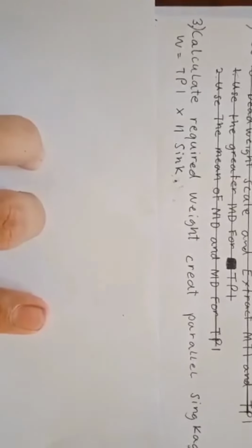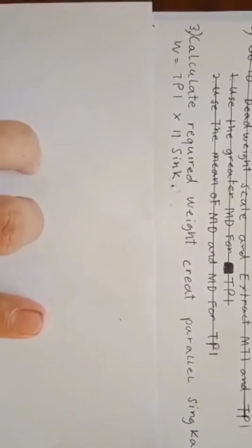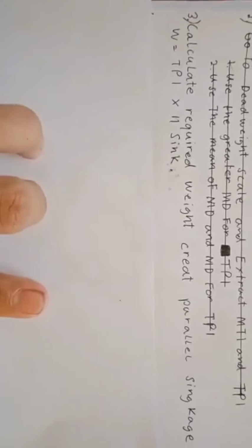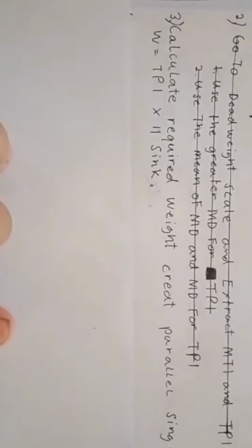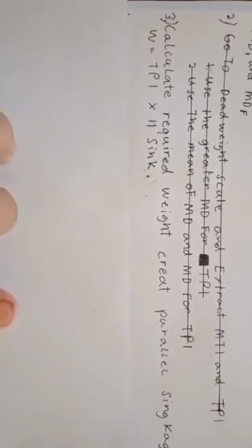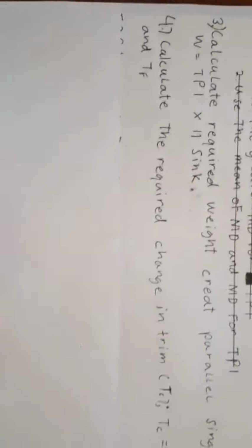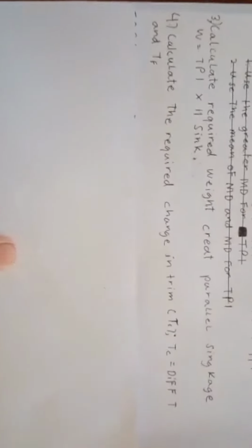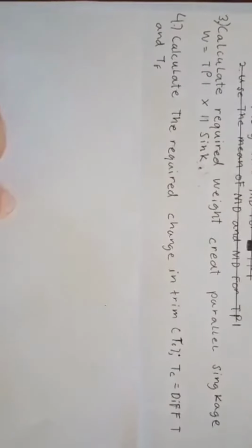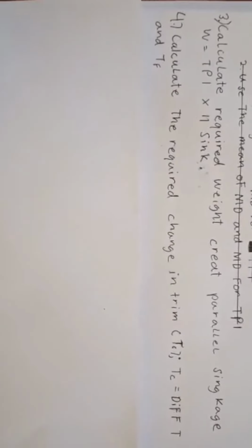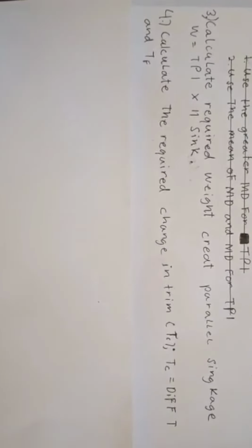Once we've sunk it 6 inches, then we'll slide the weight back. By doing that, we're going to increase the forward draft by 6 inches. But wait a minute. If we increase it by 6 inches, we're no longer at 21. If we load the weight back aft, we can change the trim by 6 inches. And that will get us back to 21 feet. So normally we'd have to go to the deadweight scale, but since we're given those, there are those givens.